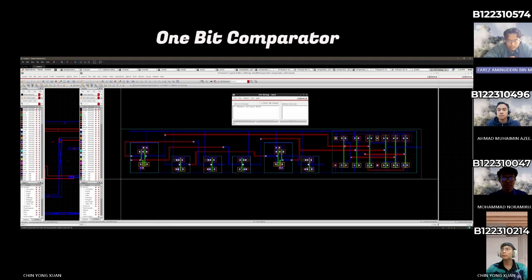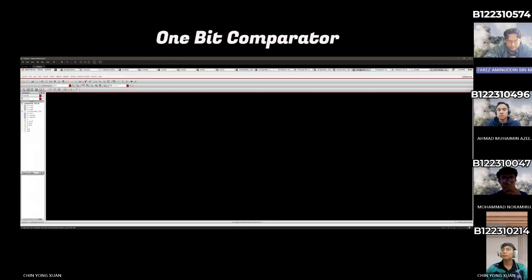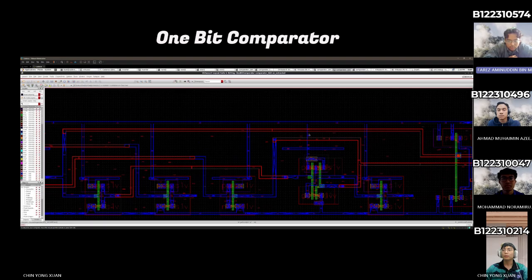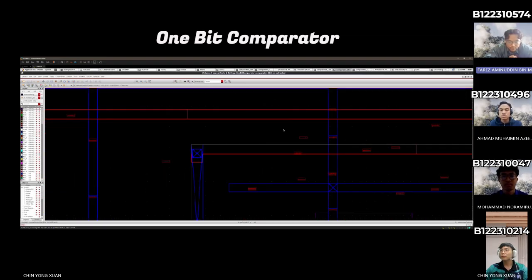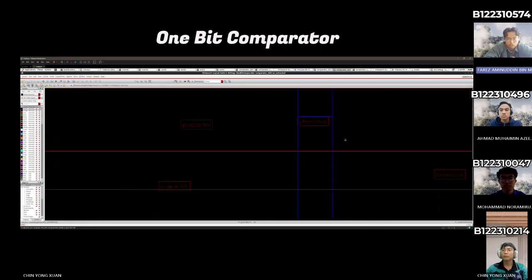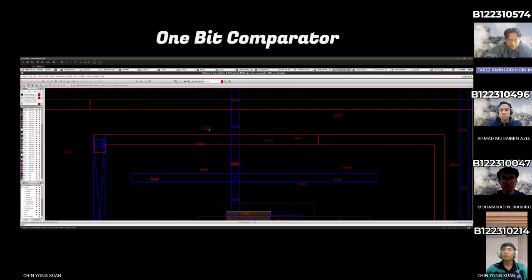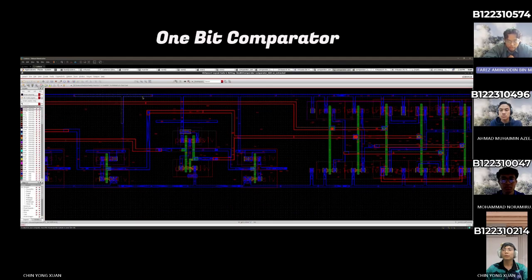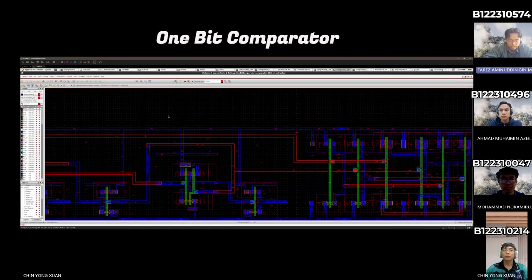An ideal schematic simulation assumes wires have zero resistance and capacitance, but real silicon doesn't work that way. Parasitic extraction bridges our ideal logic with physical reality. The software mathematically extracts all the microscopic unintended resistance within our metal tracks and the parasitic capacitance that occurs when wires cross or run near each other.